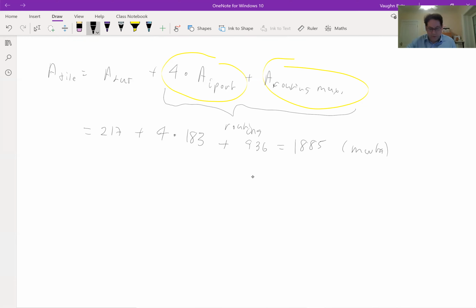And so if we actually compute what fraction of this is routing, because the only part that is actually doing logic is this part, we get that this is 88% routing area, which is big, okay? So don't neglect it. There are some papers, as I said, some old, but some recent, where they just neglect routing area because it's harder to figure out. But it's not a second order effect, it's a first order effect.